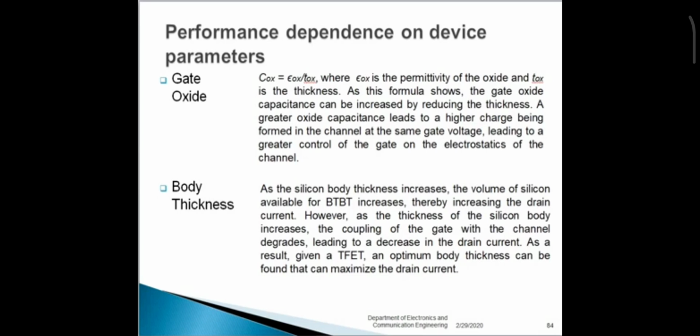This can be prevented by use of a material with high permittivity, such as HfO2 in case of SiO2. We cannot use HfO2 directly. We are using the gate stacking, in which we are using SiO2 plus HfO2 as the oxide material. By using the gate stacking, this would cause a thicker potential barrier between the channel and the gate, and the use of gate stacking SiO2 plus HfO2 has the added benefit of further reducing the oxide capacitance and increasing the gate control of the channel.